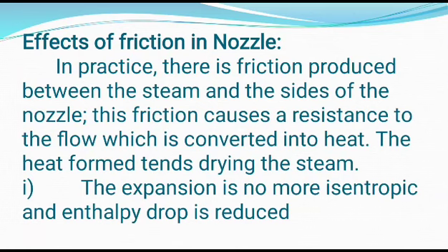The effects of friction in nozzle. There is friction produced between the steam and sides of the nozzle. This friction causes a resistance to the flow, which is converted into heat. The heat formed tends to dry the steam. The effects of friction in nozzle.